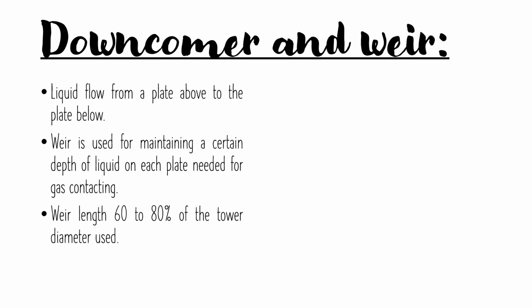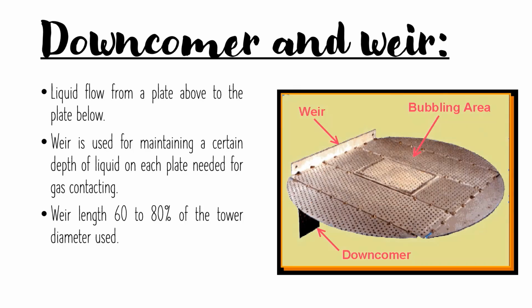As gas bubbles through a pool of liquid on a plate, a large amount of turbulence is set up, and liquid particles can be entrained by the rising gas. Entrainment is the carryover of liquid particles by the rising gas from a plate below to the plate above.